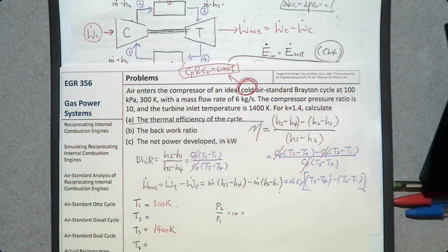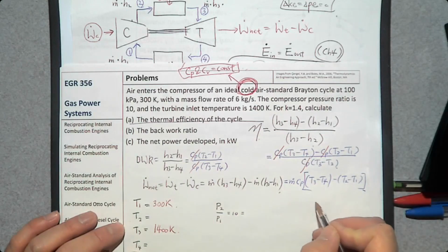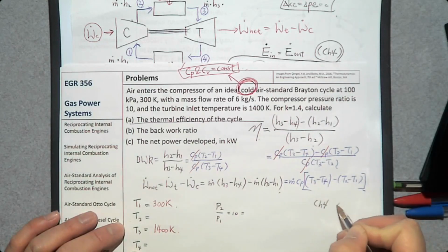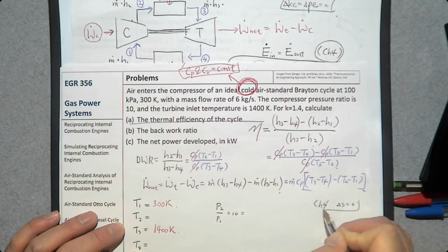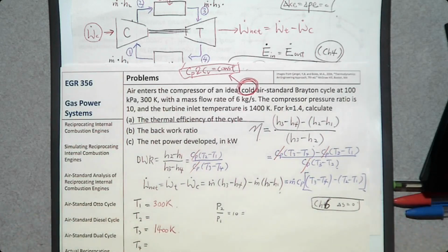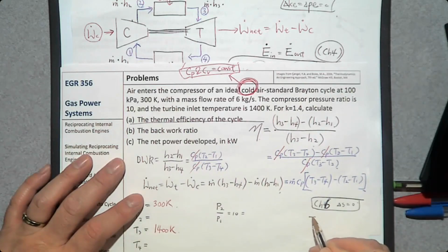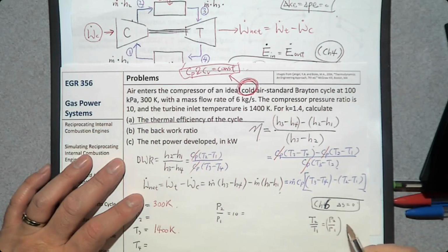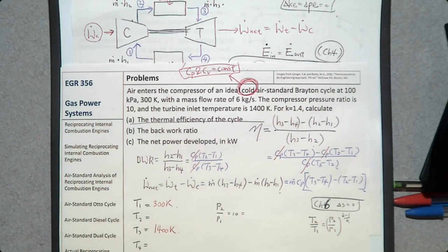Yes. In chapter 6, for an isentropic process, I'm sorry, I said chapter 6. Today is the last class, so it's time to have a break, right? So you may remember this equation. T2 over T1 is (P2 over P1) to the power (kappa minus 1) over kappa. You remember that from chapter 6.